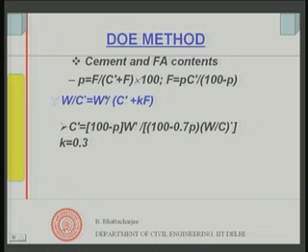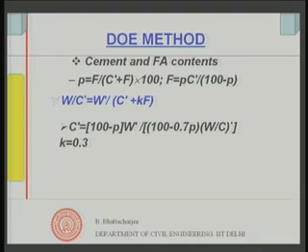By simply rearranging I can find out C dash, which will be given as 100 minus P, because I will put F from this expression. If I put F from this expression here, that is P C dash over 100 minus P, then P is known to me, because P is the percentage of the fly ash in overall cementitious, and that is the first thing I have decided. Right in the beginning I decided what is the P, because I said that you want to use 30% fly ash in the cementitious, well fine, that is what you take, 25% and so on and so forth, and that decision either has to be specified or one has to make that decision in the beginning. So, P is known to us.